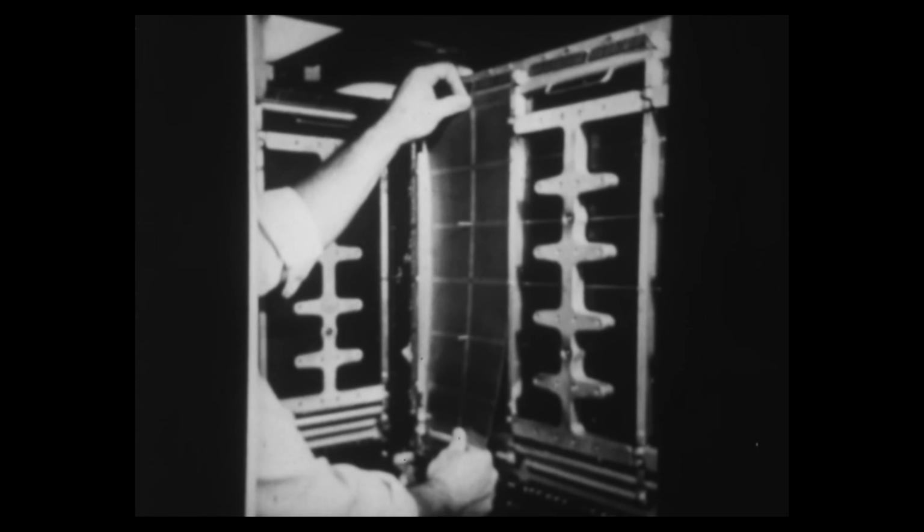This is an example of the bit plane for the balanced capacitor read-only store that we find in the case of the Models 50, 60, and 62. They all use basically the same type of storage. Again, as I said, the word size varies depending on what model we're talking about. But you can see the way that the field engineer can change a bit plane in these units.